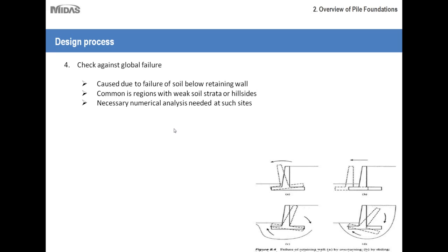Okay, then it's necessary to use numerical analysis on such sites. For areas with particularly weak soil, it's best to use numerical analysis because conventional methods are a bit too conservative and it's not really safe or realistic to use them.